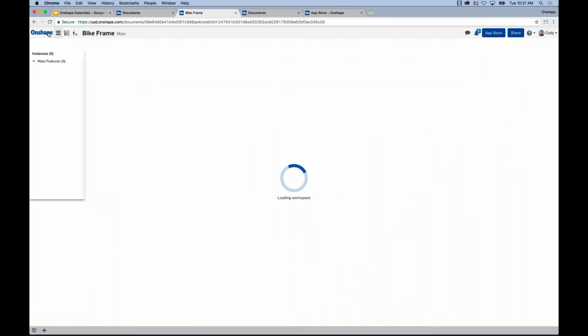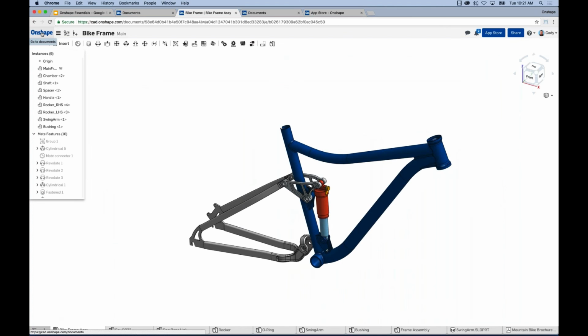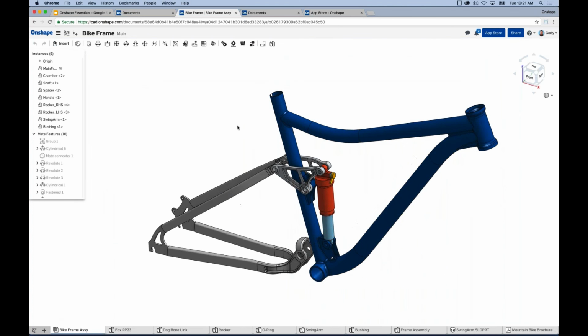So just keep in mind, if you left click this Onshape logo, it closes the document out. Next to that is the document menu. You can change the units of the document. You can change the properties. A commonly asked question: how do I give it a part number? Or how do I set the state of a design? You can do all that under the workspace properties.